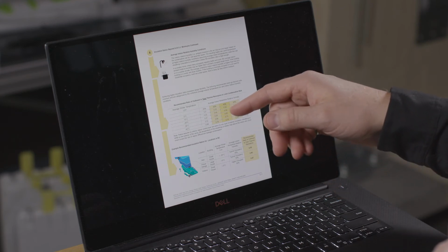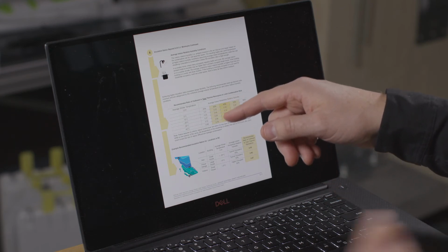With exterior insulation, you may find that you might need up to 2/3, or 70 or 80%, of the insulation on the outside before you look at the vapor control on the inside. So depending on what this table tells you, that's the ideal ratio. If you don't have it, that's not a problem. If you do have it, it sets a different criteria. So you've got your wall, you've got your insulation, you've figured out what permeance you have, you've figured out your ratio here, and you're following this through and writing things down. There are a few examples here, and generally, around 50%, 50-60%, is going to be safe for most of Canada.